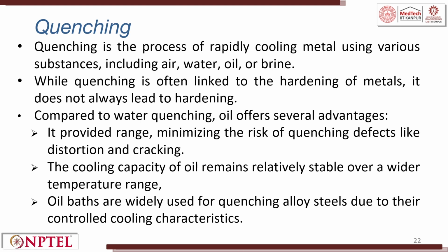Quenching. Quenching is a process of rapid cooling of metals using various substances as we have discussed earlier: brine solution, air, water, oil, etc. While quenching is often linked to the hardening of the metal, it does not always lead to hardening. It can also reduce the hardening.